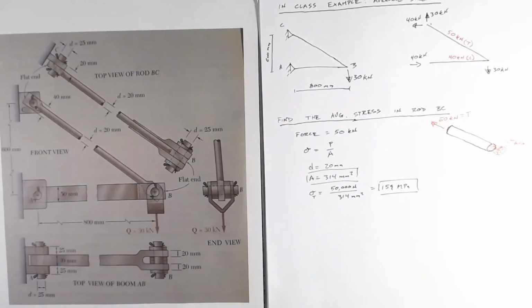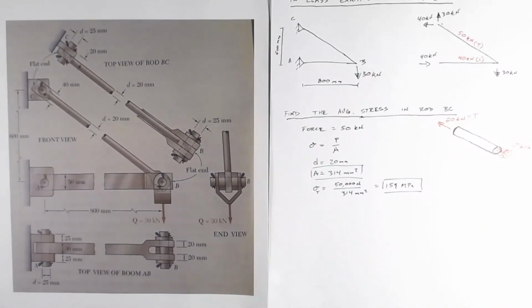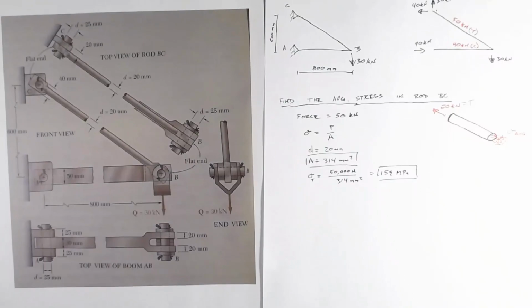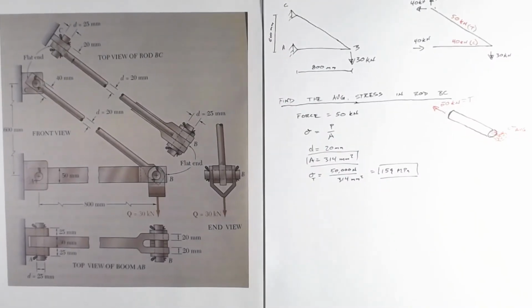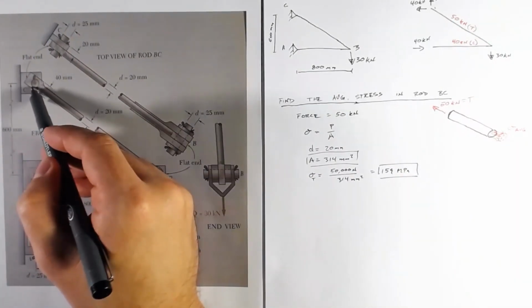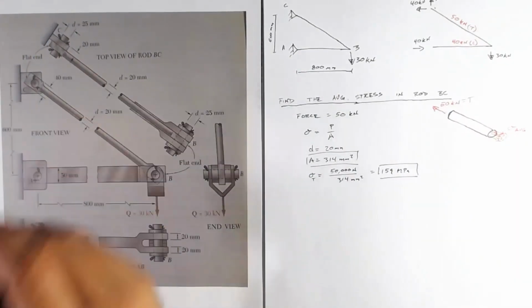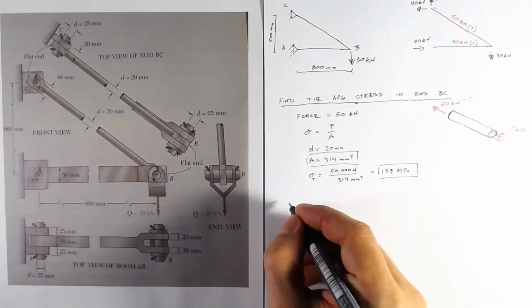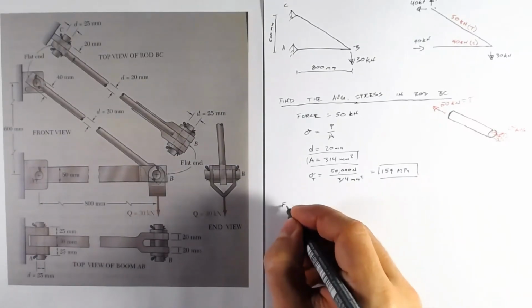Our stress is determined by the area of the section which can resist that stress, so we need to make sure we're calculating where our maximum stress is going to be. That's going to be where we have the smallest area, in the section right here where the pin is at its maximum diameter. So we'll find it at the flat end.